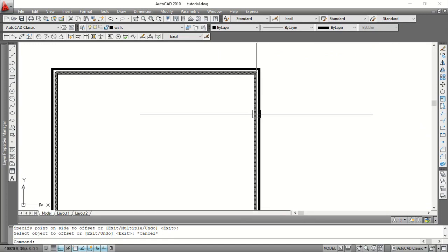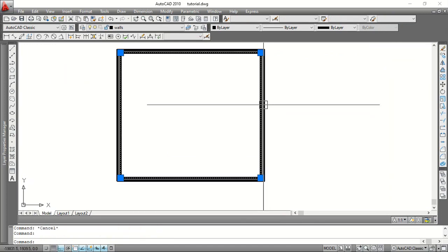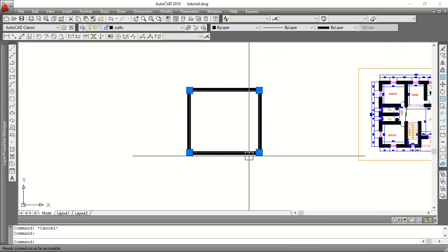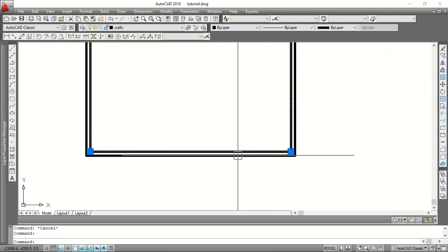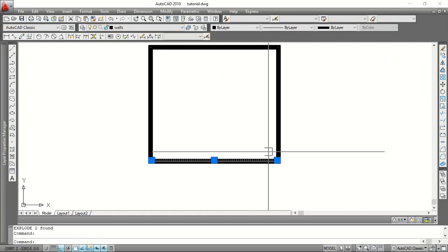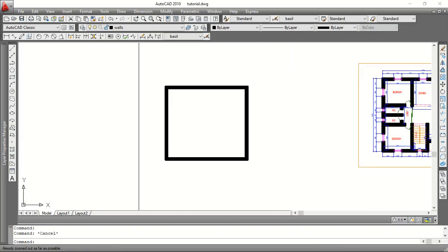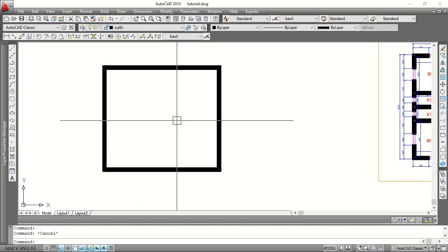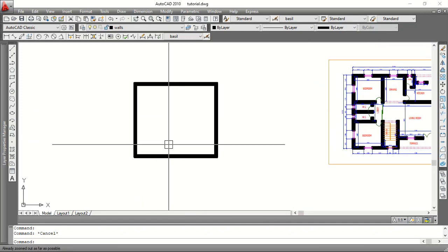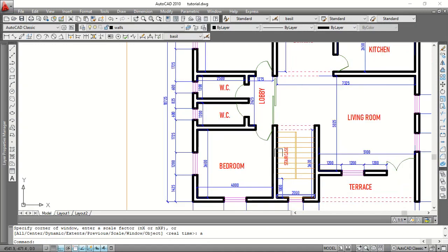But don't forget, because I use polyline, all the lines are together. Polyline doesn't break lines. But the most important thing to do once you're done with this is highlight it, press X on your keyboard to explode it, then enter. So all of them are now independent. Okay, it makes your job easier. All right, so whenever you're having issues, maybe you're trying to zoom and you can't zoom perfectly, just type Z, enter, enter, everything will come to your screen.